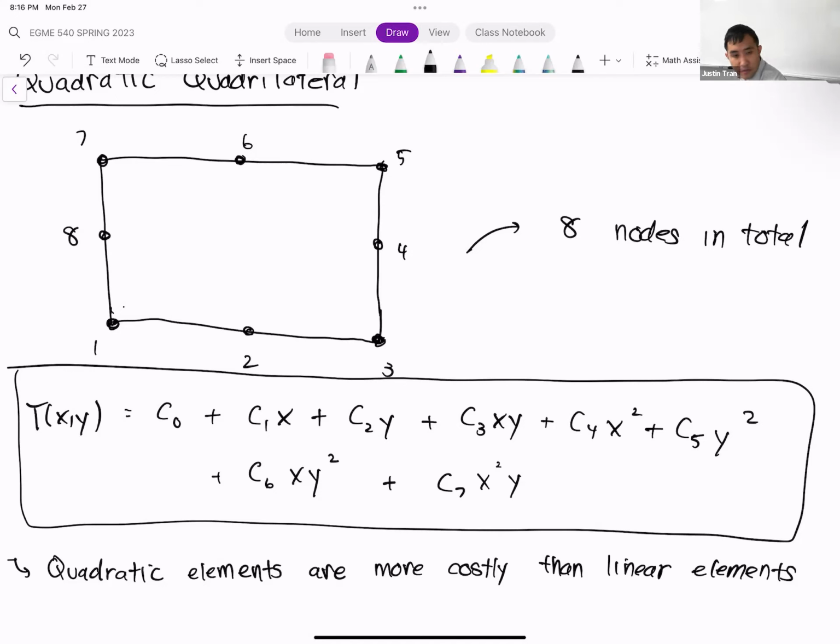Okay, sure. Not related to the lecture, but for the homework assignment, can you quickly show how we can change the dimensions for part 5? Oh, yes. So when you're changing the dimensions in activity 3, you have to do that back in Design Modeler. So you have to close ANSYS Mechanical and then modify the geometry in Design Modeler. It's a separate program for it.